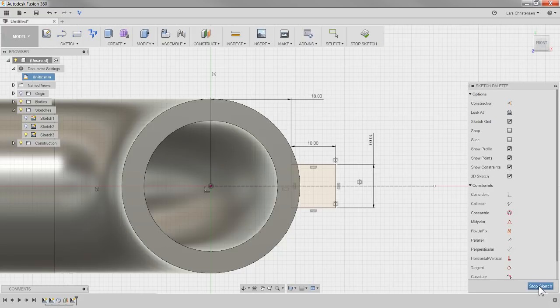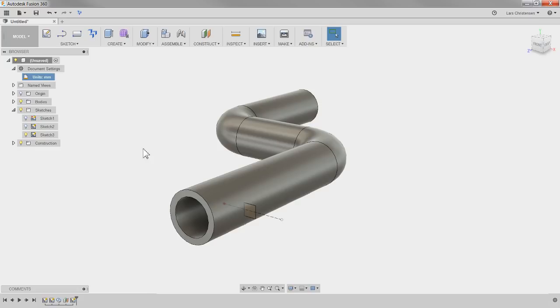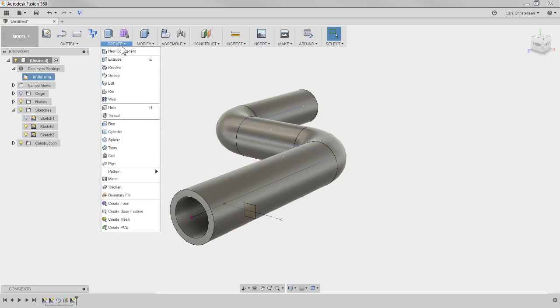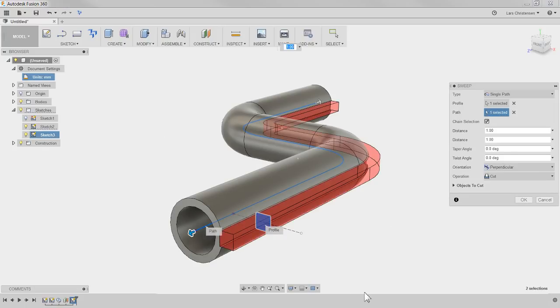See, I can go out here, to my sketch for my profile, and if I go back and turn on that original path I created at first for the tube, I can reuse that one again, even though these two don't even intersect one another. So this path has been used in two instances now.